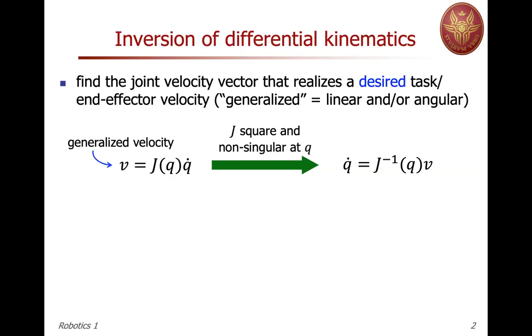Now, indeed, we can imagine that we move with this joint velocity, so the configuration of the arm changes a little bit. We apply this velocity for a sampling interval, which typically is 1 millisecond or less or more, depending on the control architecture that you have. So you're moving for a while, so you're changing configuration.